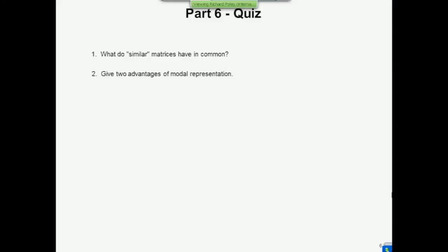2 advantages of a modal representation, I guess at this point. Yeah, simplification. The pathways from the input and the output to the output are much clearer to visualize. Right? Because of the first property that we just said, the properties of controllability, observability, and so on, and detectability and stabilizability, all those things are much easier to visualize than constructing a controllability matrix, for example, and looking for a rank. So it's much easier to visualize those things.